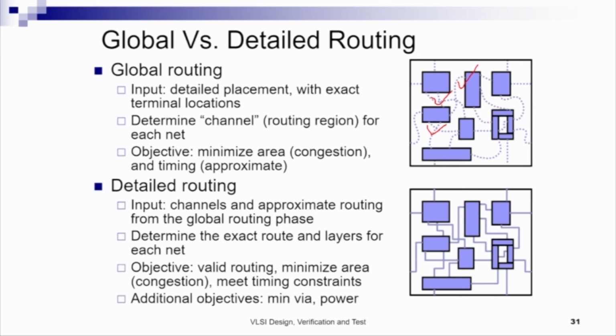should pass. For example, let us say if we consider this net. If we consider this net, we found that it should go through this channel and then this channel and then this one here, right. So, this is the position it should take. There could be other more complicated ways in which you route a particular net. So, the objective is to minimize area or minimize congestion.